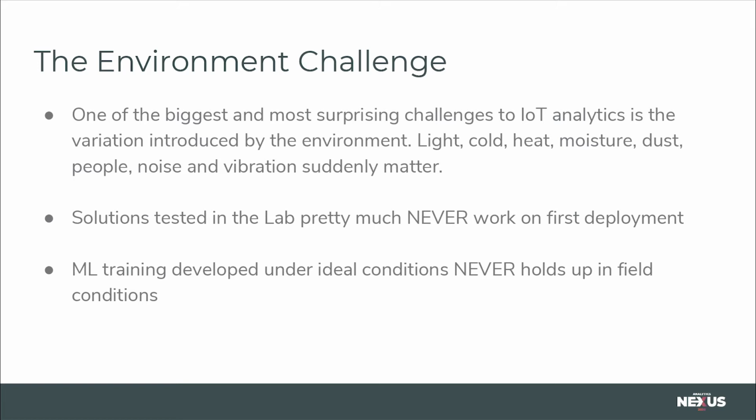We had no idea what was going on. It was like tomorrow was the ship day for these devices. They'd been running for 2 weeks, and as we got them ready for shipping, suddenly every one of them had failed. And what we realized after a little bit of time was that in putting the covers on, we'd been running the devices uncovered. When we put the cover on, the devices all overheated. Just that simple.